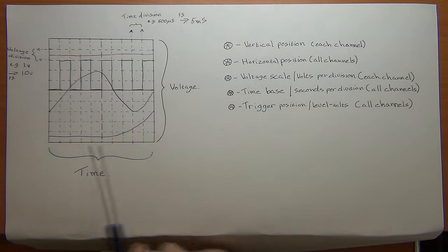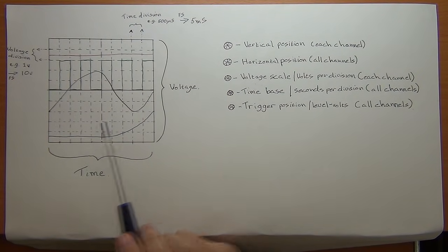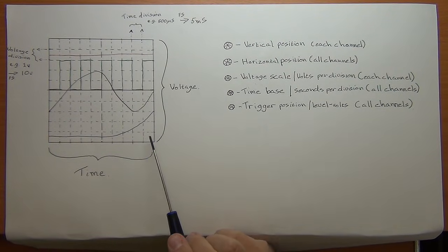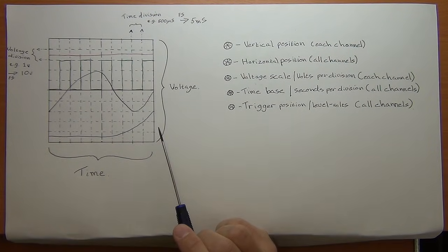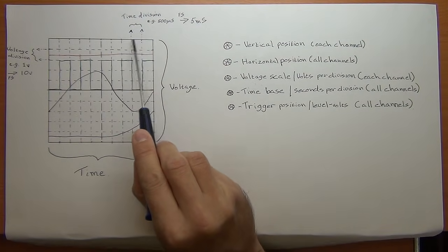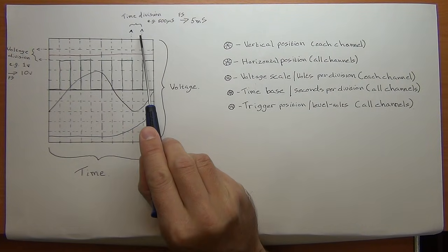Now that's known as your time base, and when you set your oscilloscope you can set what that time base should be, or it can be automatically selected for you, obviously, because you might not know the best time frame to view a signal. And as I've highlighted up here in the example I'm going to show you, each of those little squares is that division.